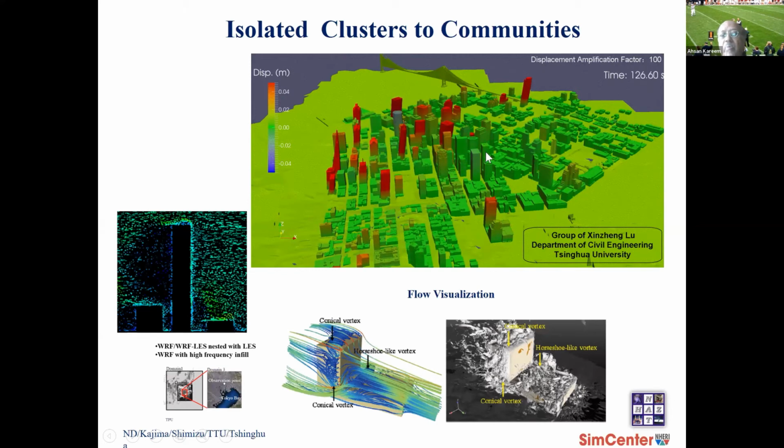And I think down the road, we will see that, in old days in fluid mechanics, we used to do smoke visualization or dye in a water tunnel. I think very soon we'll have all these things digitally done. And here is one example. We did the model part of the city of Houston after a windstorm while investigating the glass damage. And here are some of the flow patterns which help us to understand what was happening in this street canyon, which was corroborated with the flow visualizations. And later we did pressure measurements on the building to see what really was happening in that particular case.